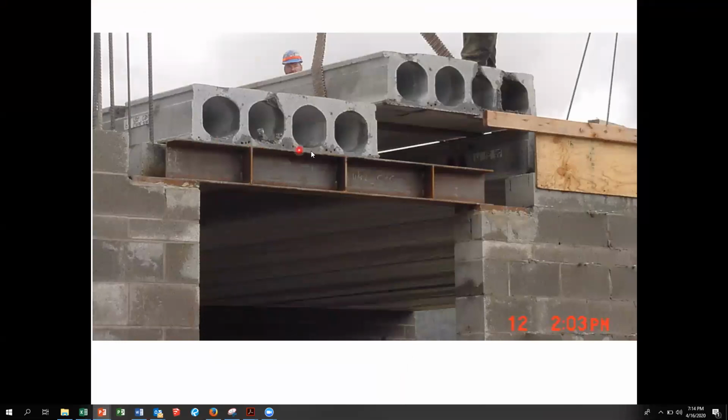Okay. Here's a good shot. This is a small piece of steel that's used for an opening. Excuse me. So you can see right here is an open web bond beam. It's got that knockout. I don't know why they haven't knocked that out yet. And then they'll put another piece in here, and then they're going to grout that. And then there's the formwork that they're going to put concrete between the end of this hollow core plank and the face of that formwork.